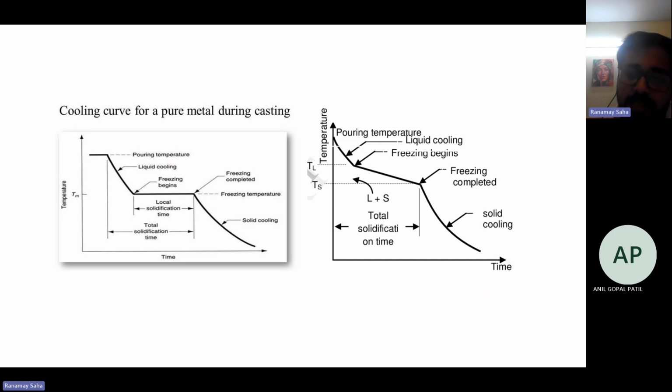So the temperature gradient gives rise to a compositional gradient also. So you have different kinds of grain structure that are built up, starting from dendritic grains, then more columnar grains. So these varied grain sizes or grain geometry which are being formed give rise to variation in density within the particular casting, which is an alloy.